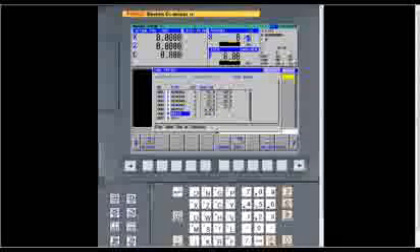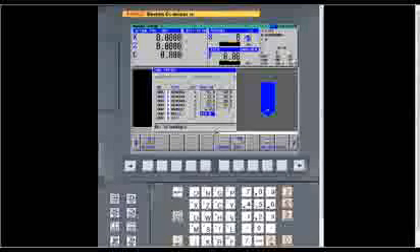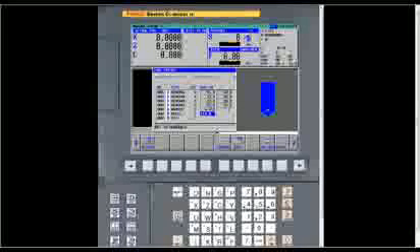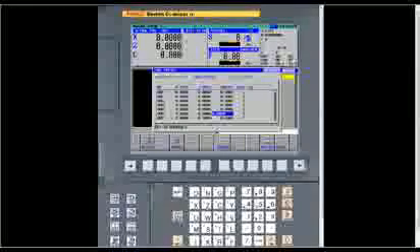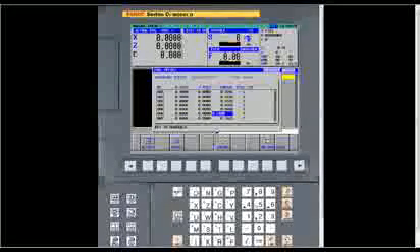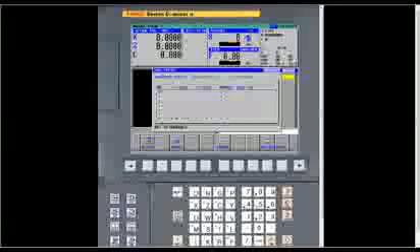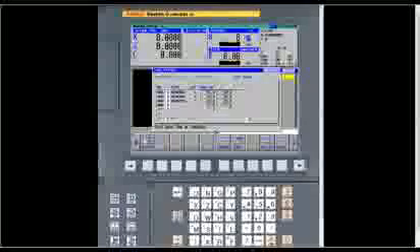Then for a drill, all it asks for is the orientation based on your type of machine, and then the angle on the drill. Then also one note for when you're doing this, you need to go back on a drill. If you want it to show up in the simulation, you do have to put a radius value here, because then it will actually show that size drill. So it's important you put a value in there for a drill.